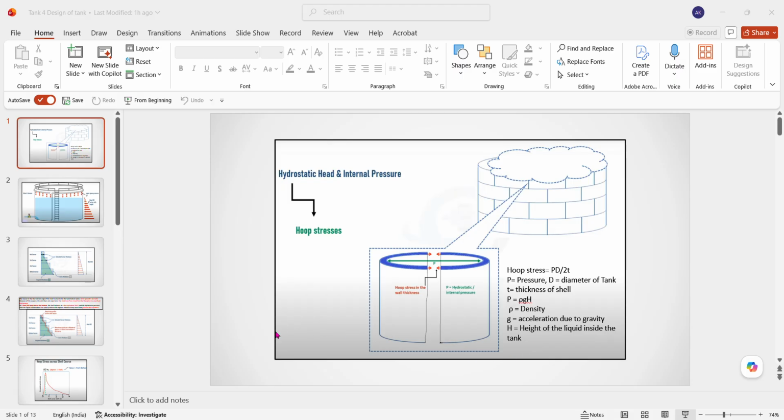This is for the bottom course of plate, then the top course and the subsequent courses. The smaller second course is welded with the thicker plate of the first course, so this will act as an anchor point. This will not allow any movement, so a free cylindrical shell will not be here.